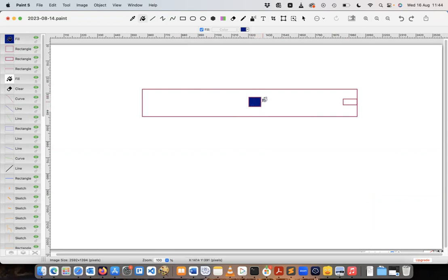So after the spill, clearly petroleum is going to diffuse in all directions here. We will make a simplifying assumption that it will instantaneously mix in this direction. So you have one concentration that applies here. And then we are going to look at the diffusion in those directions. It does look symmetrical, so we can anticipate that we will have a boundary condition, a kind of symmetry boundary condition that applies.